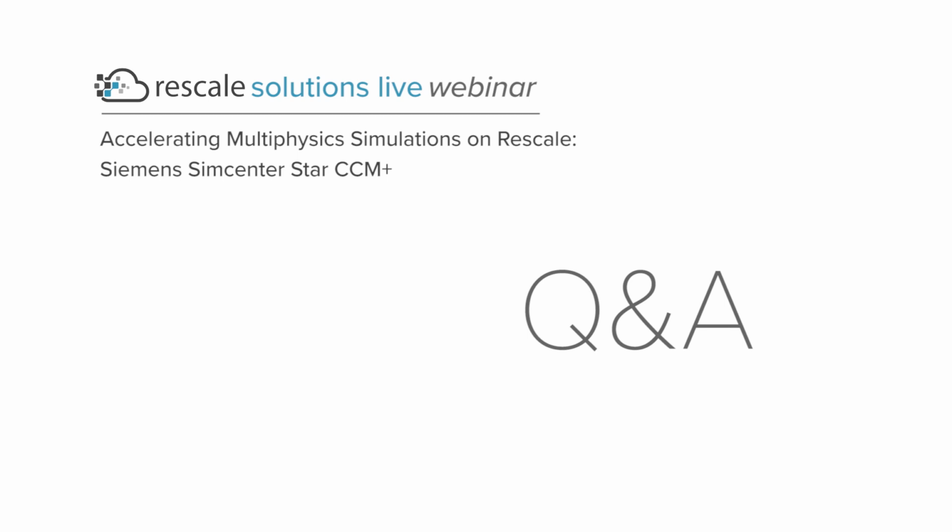And let me add something. That's why we generally recommend to stop your single design simulation not based, for instance, on the number of iterations, like 500 iterations each, because what can happen is that one design totally converged with the 500, whilst another design was really not converged at all. So we should always stop our job based on some physical parameters, like the stabilized velocity at the outlets of your configuration. So this is my recommendation.